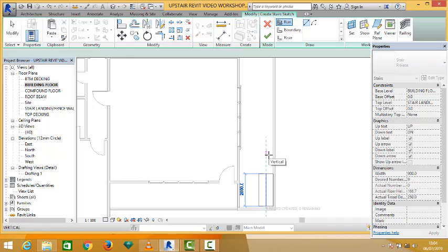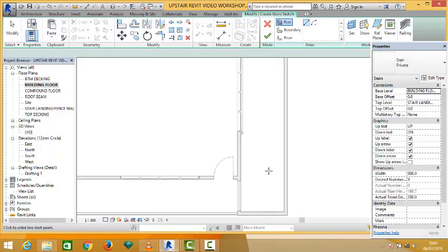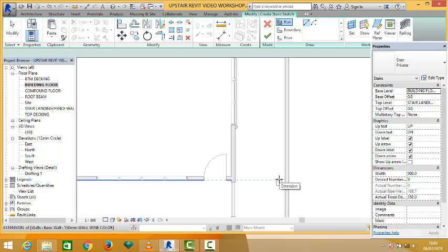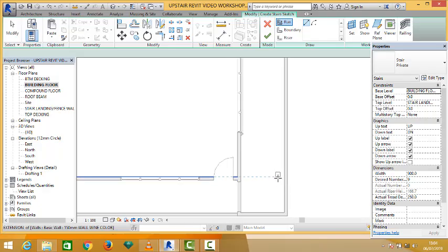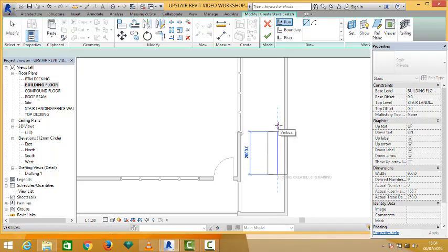Okay, good. So the nine stair, sorry, I am not supposed to begin my stair from that particular place. I'm supposed to begin from somewhere here, because we are going to need a space between the actual stair itself and where you have the door, so that when you open your door you have enough allowance to move in before climbing your staircase. So I begin my stair from this position.